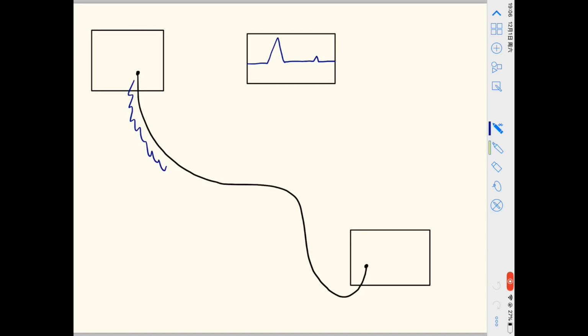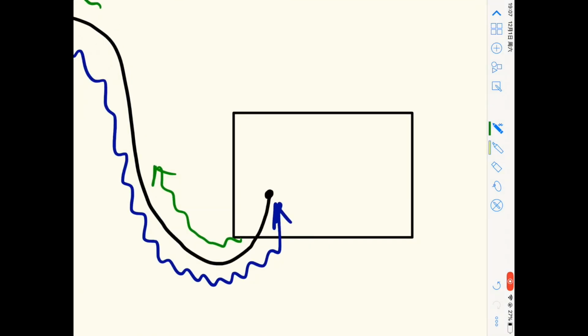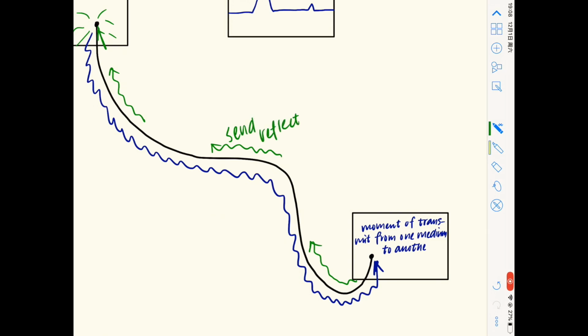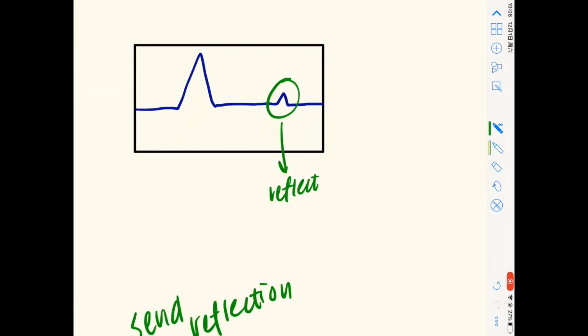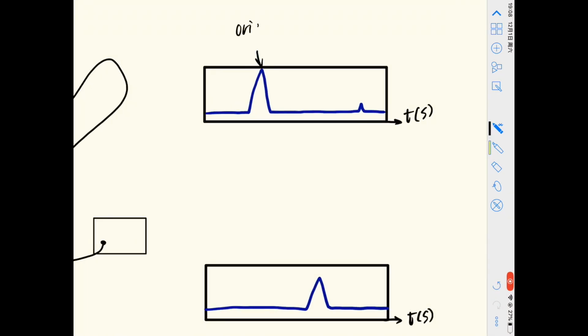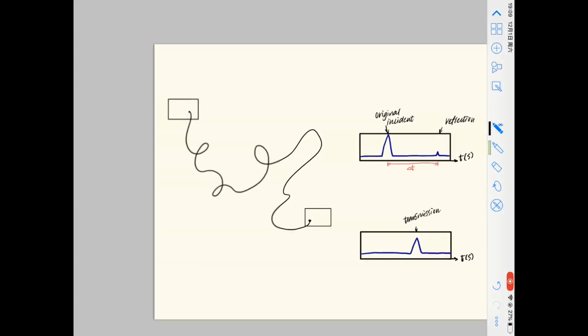Now that we know the characteristics of an electric signal in coaxial cables, we can measure the speed that a signal travels through a specific cable. By connecting a pulse generator and an oscilloscope, we can show the moment when a signal arrives at a machine. In this case, if we have a long cable, we can measure the difference between the first incident of a signal and the reflection at the very end of the cable, and use that to measure the time it takes for the signal to travel to the end of the cord and back. Therefore, knowing the resistance of a particular cable, we can calculate the speed of the signal it travels in.